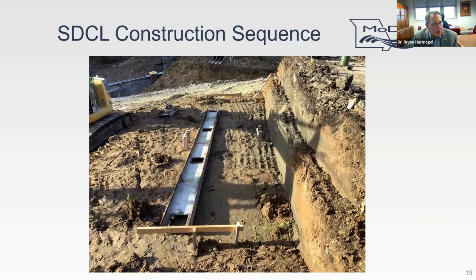The Lehman Construction Company was pretty innovative. Of course, you've got to take down the old bridge that's there. And so they used the girders that were there as a template to drive their pile. And so you can see, excavate, get ready, survey where you're going to put the pile. They've got the template there ready to drive the pile.